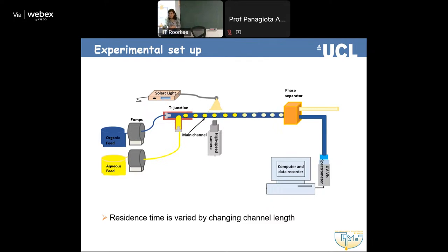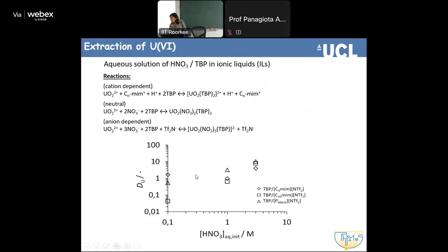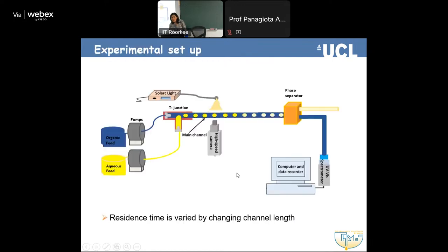And in a way, that's all right, because that's how we work. And then we might have to have another stage and another stage. However, if this partition coefficient is quite high, then it means that a lot of the material would have transported. Not all, not at equilibrium. I actually don't want to be at equilibrium, because the closer I am to equilibrium, the slower the separation happens.